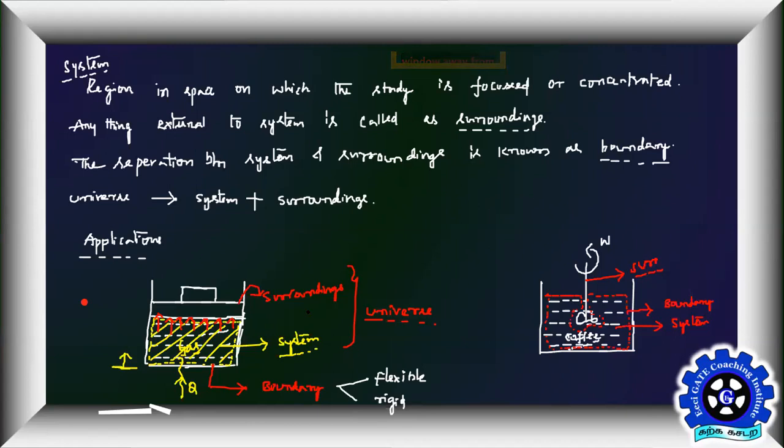Nowhere do they say take this as the system, take this as your focus, take this as your concentration. Very rarely do you see those kinds of terms in the exam or in any question. Indirectly, what does that mean? Say you have a fluid sitting inside the cylinder. Now I'm adding some heat and it is doing some work. The question will be: what is the amount of heat added to the gas, or what is the amount of work done by the gas? It is indirectly saying to assume the gas sitting inside the cylinder as your system. Is it right?